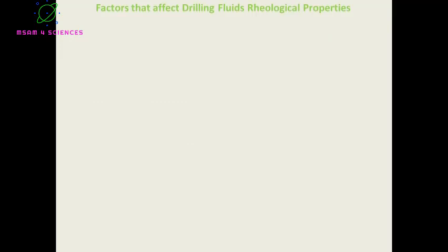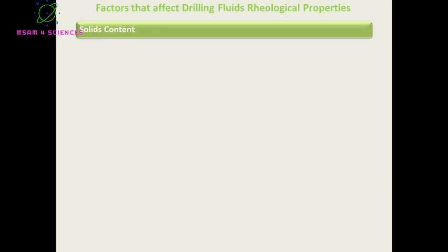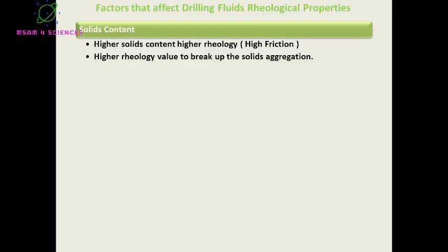There are some factors that affect the rheological properties. We'll start with solids. When the solids content in the drilling fluid is higher, the rheological properties will be high, and there will be higher stress needed to break the solid aggregation.